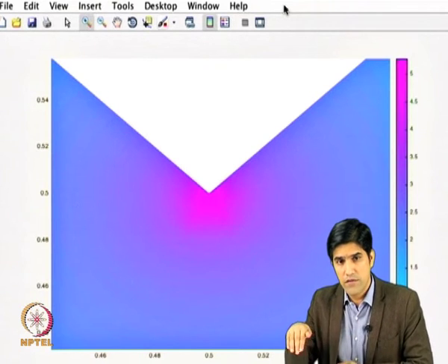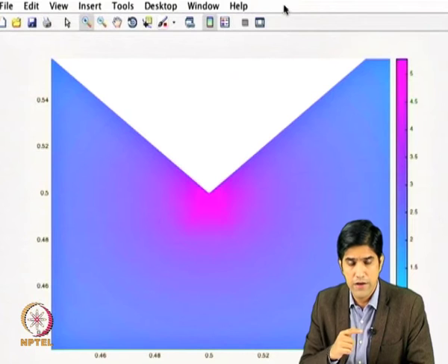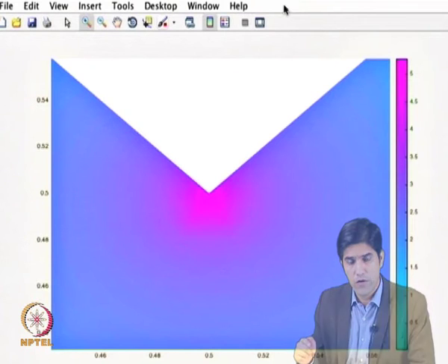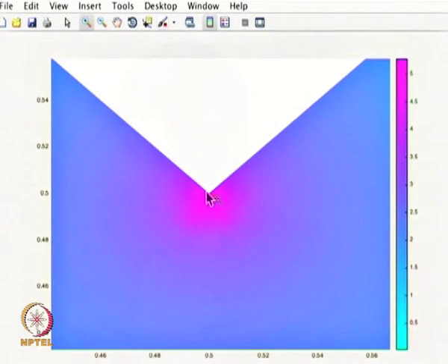So remember the curve that we had: refining will lead to reduction in error because of one reason, whereas it's going to increase the error for a different reason. And that is what we have also showcased in this case. Although we have refined, globally the solution is replicated in a good way. The electric field at this point and this point is nice, whereas at sharp edges the error is exaggerated much beyond our expectation. You see that it's going to a very high value.